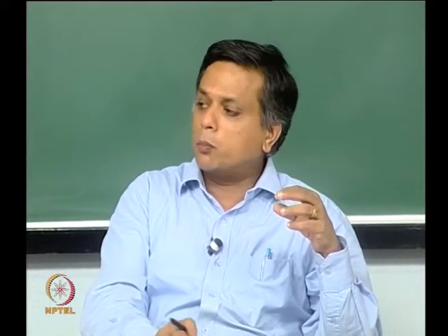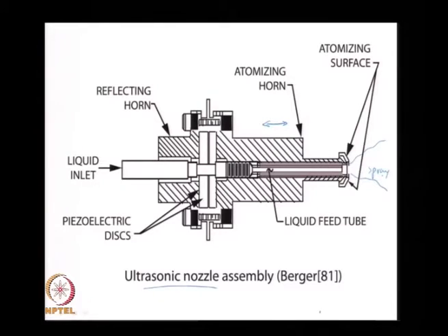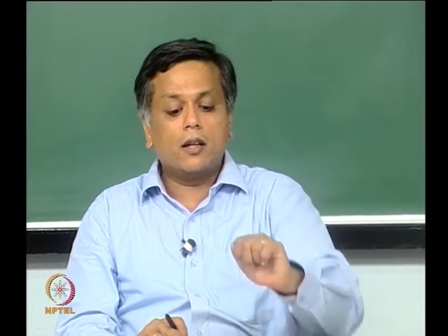Okay. Now, this is very efficient in the way it uses the energy, because all the energy that we put in the form of the ultrasonic nozzle is entirely transferred to the liquid. The liquid inlet has a pump that drives the liquid through this nozzle that is independent of the energy source. The energy source in this case is the piezoelectric discs that cause this mechanical movement of the horn, and the liquid flowing through the nozzle is due to some other source of push coming from the liquid inlet side.